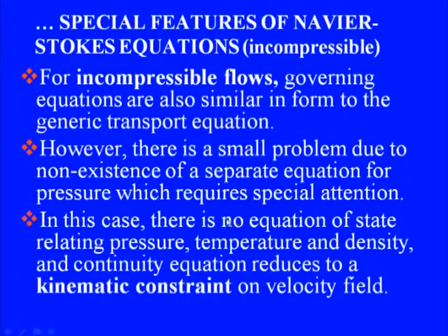So, this particular feature is what requires special attention for the solution of incompressible flows, and that would be one of the issues which we are going to address today. Okay, so, let us remember that in the case of incompressible Navier-Stokes equation, there is no equation of state which relates pressure, temperature and density, and in this case the continuity equation reduces to what we call a kinematic constraint on the velocity field. We will have to say that divergence of V is 0.